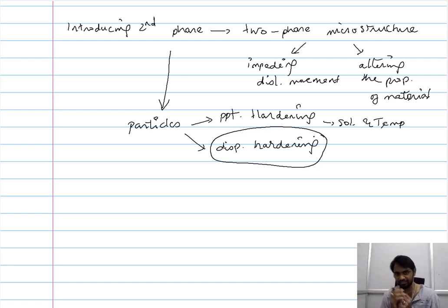Since the processing technique varies, you have a wide range of combinations, and on top of it, the phase fraction and size of the phases are not disturbed by the temperature. Dispersion hardening is considered preferred for producing the microstructure with dispersed precipitates that enhance the creep resistance.